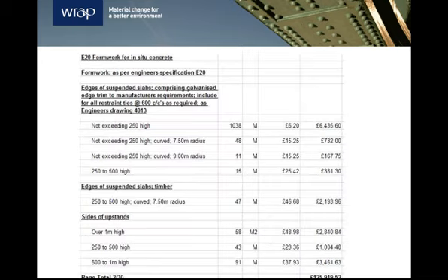You can also exclude items that you know for sure won't produce any waste. These metal formwork items, for example, will definitely be kept for reuse on other projects. As these are valuable and won't be wasted, they won't improve the accuracy of the tool's waste estimates, and we could choose not to include them in our project. If we were interested in recycled content, however, we might choose to include them, because all metal contains recycled content. Also, if these items were previously used on another project, we could consider them to contain 100% recycled content.